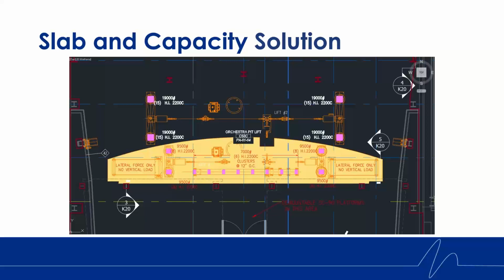A jack slab has a limitation of only 3,300 to 3,500 pounds capacity per canister, and to handle loads above that often requires nesting canisters too close together. An isolated pouring form, however, allowed close nesting of the isolators, thus allowing the proper capacity to be provided without compromising the integrity of the slab. Kinetics offered two additional solutions for the isolated pouring form, which aided in making the best decision for the project. In this case too, consulting a Kinetics rep in the design phase to review isolation constructability could have saved months of delay in determining the best way to remediate the situation.